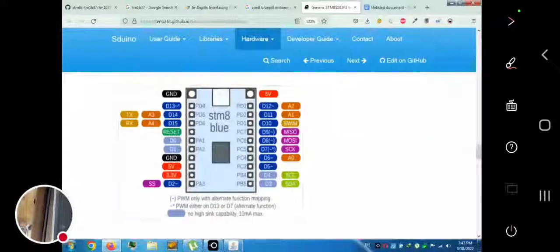So if you are using the STM8 standard peripheral libraries, you may be using GPIO-C and pin 4. GPIO C4 and GPIO C5 would work if you are using the standard peripheral libraries.